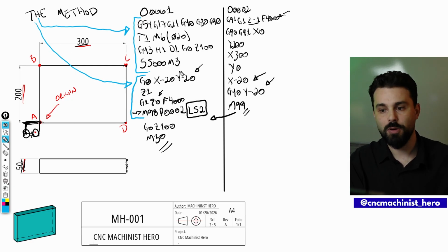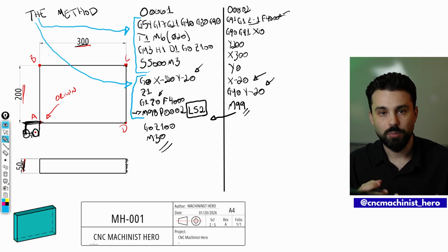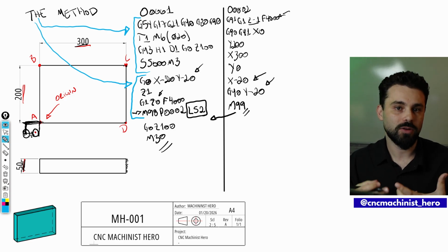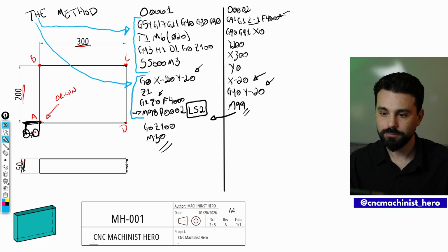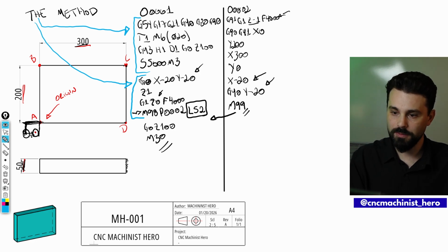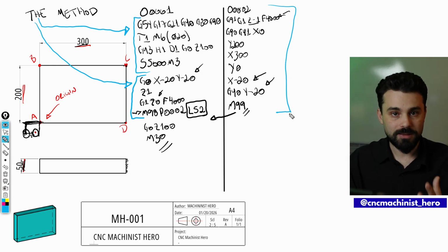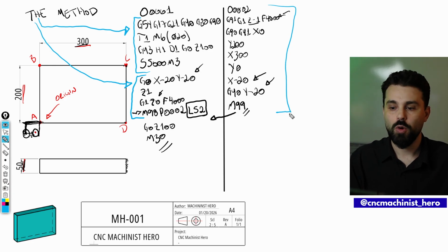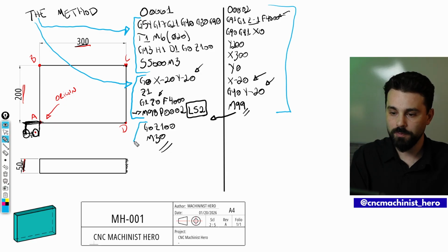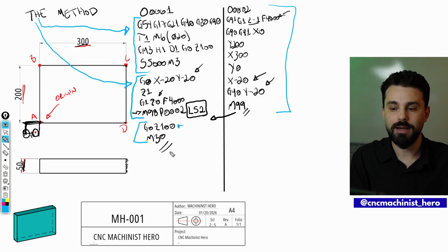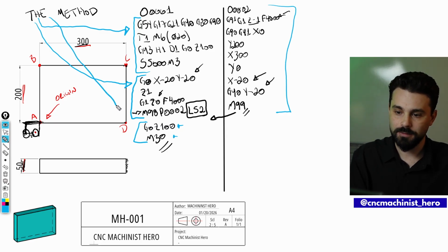So this is the part of the program that we program the tool path, where we want our tool to go in X, Y, and Z. So it's going to read this part, and from here it's automatically going to jump to our subprogram, and that's our tool path. When it reads this and we complete our part, we're going to end our program with safety, going back to the same height as we started, and M30 to finalize our program. So this is the end.